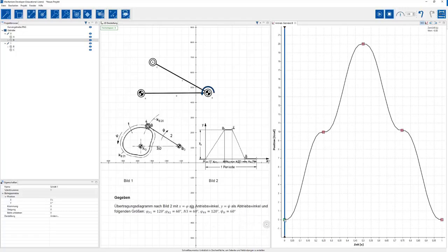Let's leave the first point at 0 degrees. That's our reference. Based on this line, in this assembled position, this would correspond to 0 degrees. At this position, we want a lift of 60 degrees. Now the lift is rotated by 60 degrees in this direction. So in this direction it is considered positive. However, in this case we are not in the positive direction, so mathematically we have to assign it as negative.